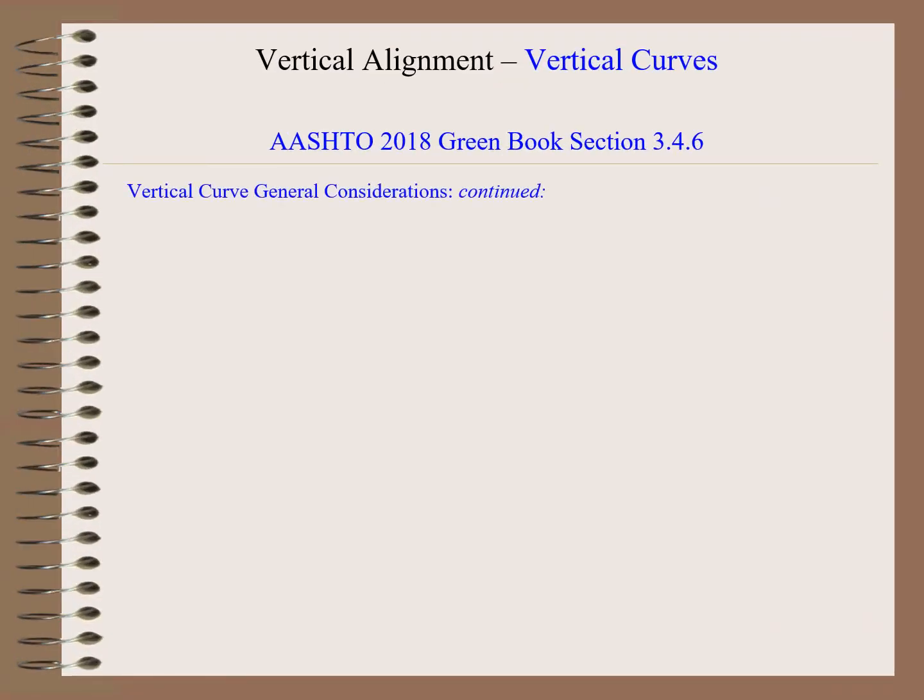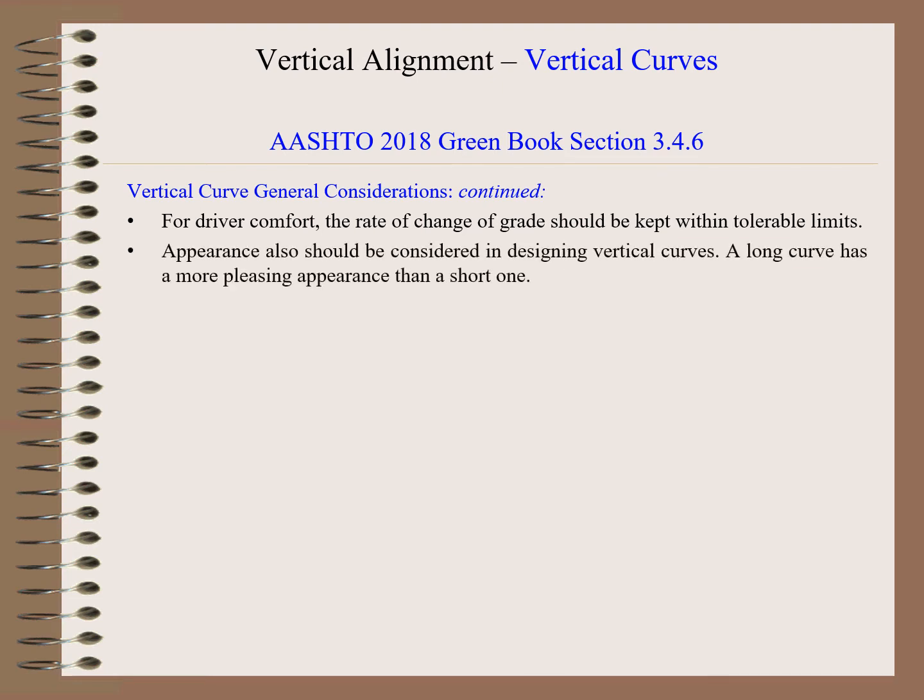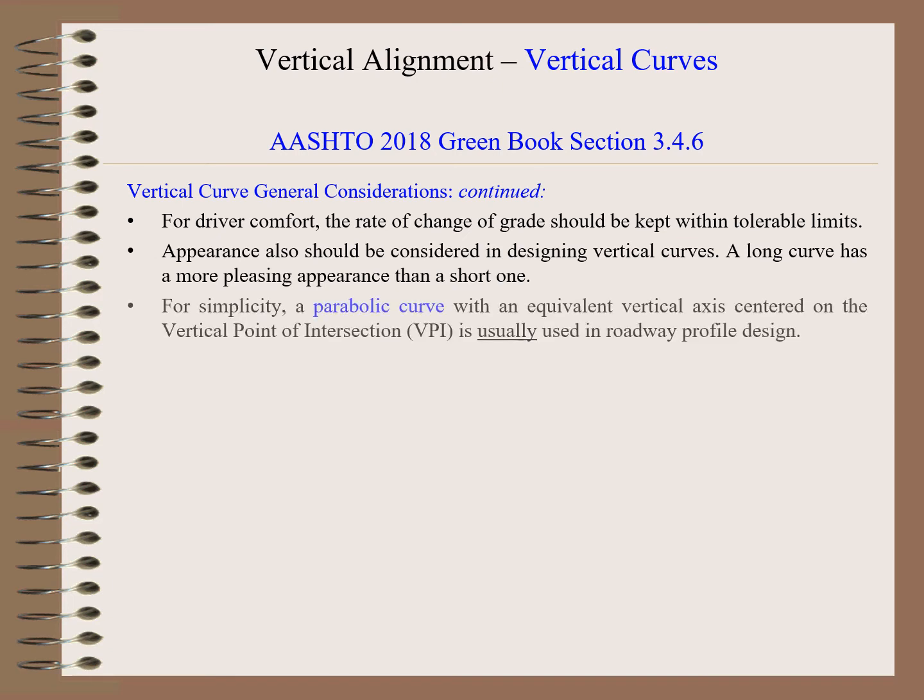Some more vertical curve general considerations are: for driver control, the rate of change of grade should be kept within a tolerable limit. Appearance should also be considered in designing vertical curves. A long curve has a more pleasing appearance than a short one. For simplicity, a parabolic curve with an equivalent vertical axis centered on the vertical point of intersection, the VPI, is usually used in roadway profile design.